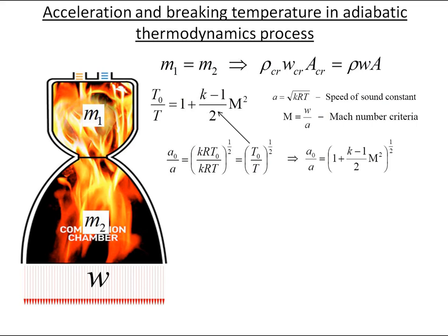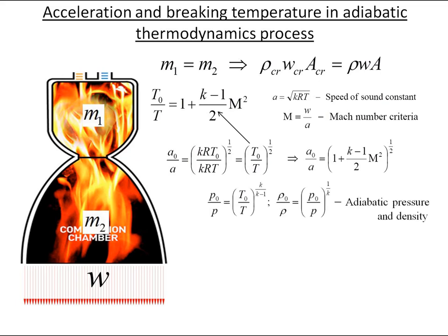We take such an adiabatic process equation from physics textbooks or Wikipedia. Express the pressure ratio through the temperature equation and we get such an expression. Insert the newly derived pressure into the density equation, and after some mathematical manipulation we get such a density ratio equation.